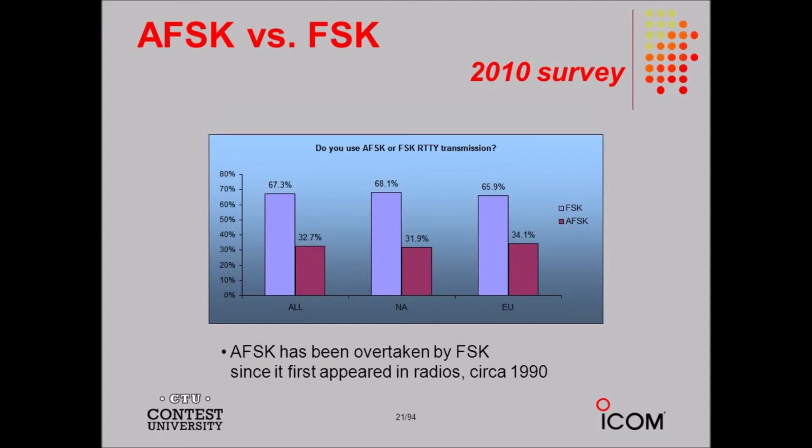modulating signal. On-off keying. The simplest form of modulation involves on-off keying of the carrier. We can key the oscillator of a radio transmitter to send Morse code, one of the simplest known binary digital modulation modes. The duration of a Morse code dot equals the duration of one binary digit, more often called a bit. A binary digit is the smallest or shortest possible unit of data in a system whose only two states are on and off. A dash measures 3 bits in duration.